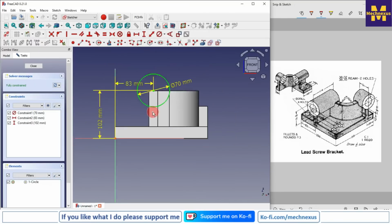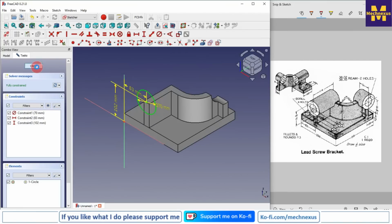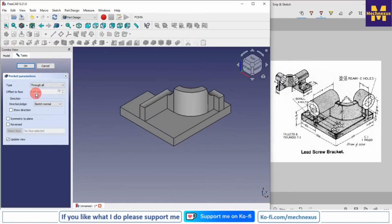I move my dimensions, switch to the isometric view. I will close it. I will select the sketch and click on the pocket tool, and I will say simply through all.